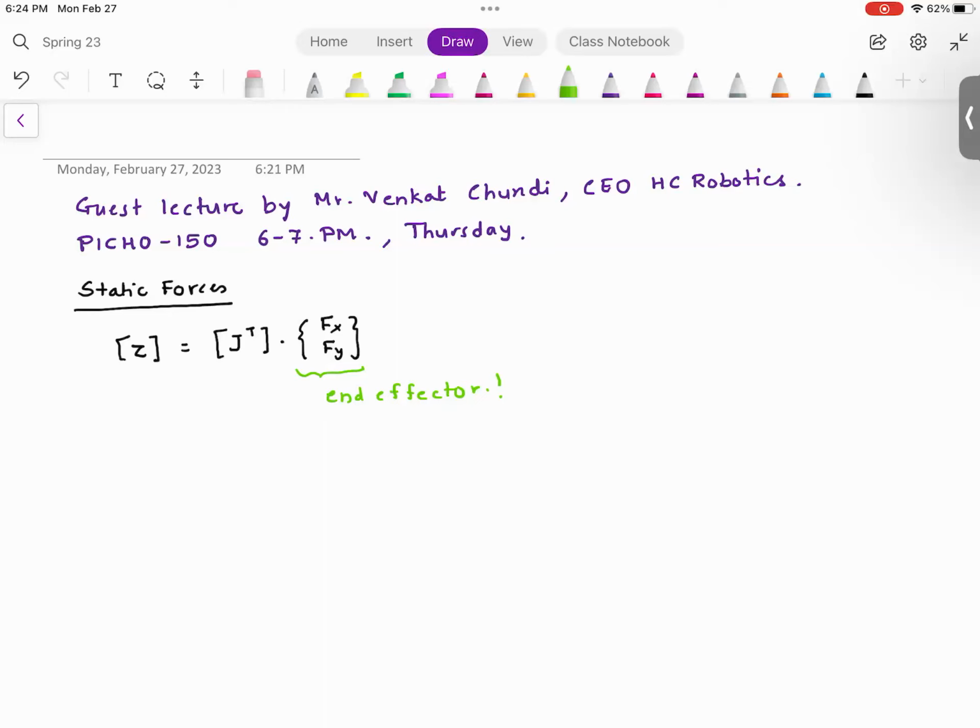Here is what happens, and this is a very practical robotic problem. You perform robot kinematics, you perform inverse kinematics, you find the angles, you solve the dynamics, and then you add an end effector. And what happens is you will see that your angles get off. Why do they get off? Because the inertial properties of the robot change.